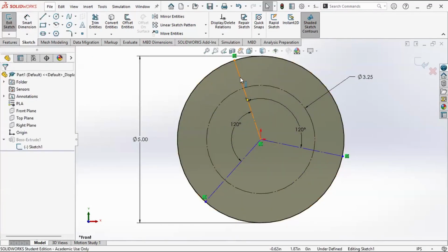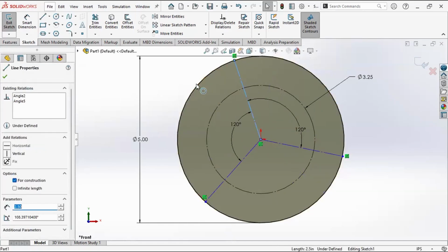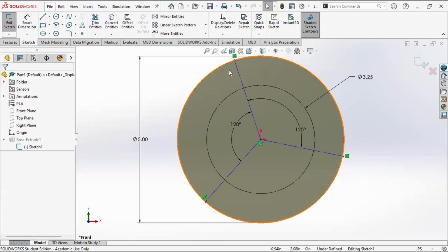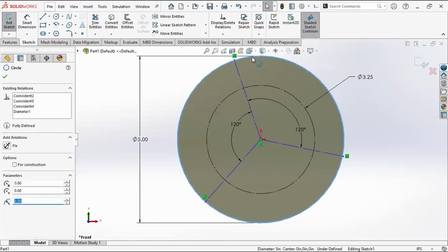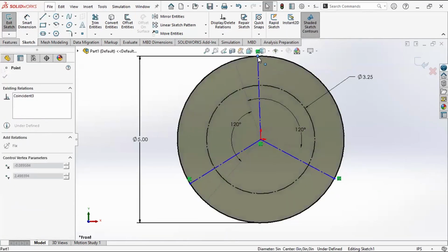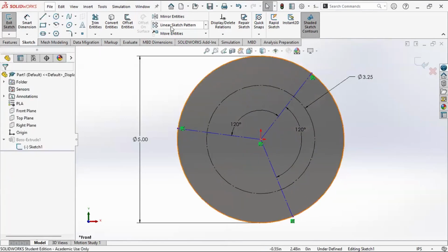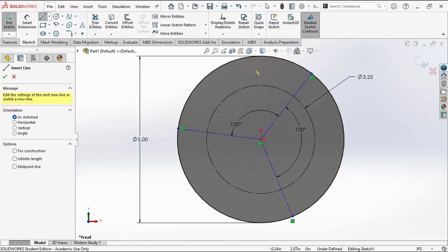So I want to also select one, and it doesn't matter which one at this point, but select one of these lines. And I want to do one of two things. When I created the circle, I also got several points on the diameter of the circle. And if I were to draw another line, I could show you, you can automatically get a coincident constraint here. At the top, notice the little yellow diamonds around the circle. At the sides, at the bottom.